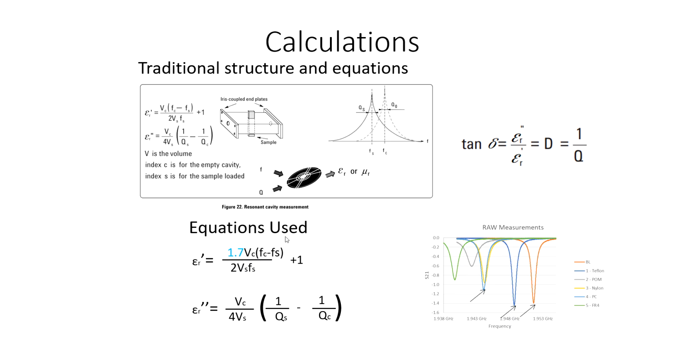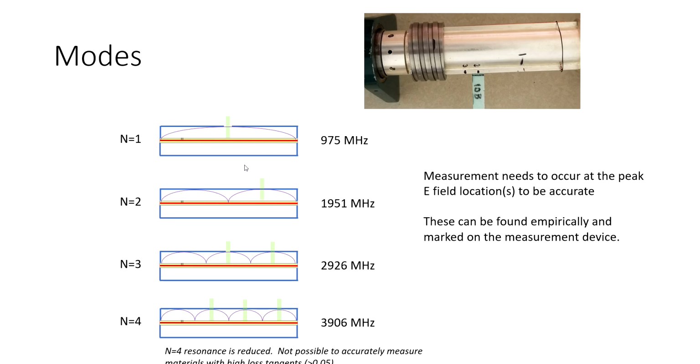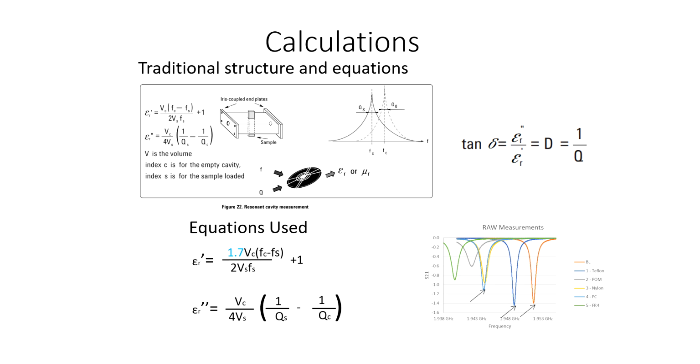again, we are looking at a cavity which is a symmetric cavity roughly, but it has the coax running through the center, not intended with the original equations, and it also has the sample which is offset on one side, so it's only loading half the chamber. It's not actually going through the full chamber. And I think because of that, it throws off the calculations a little bit.